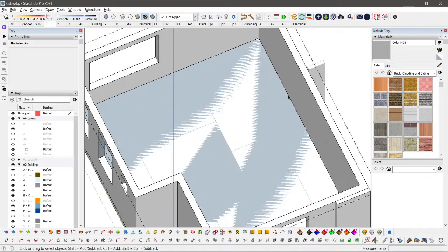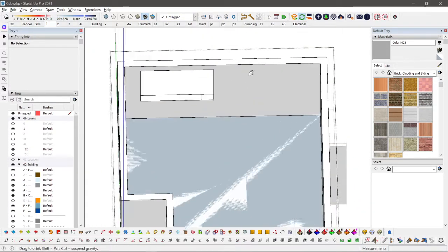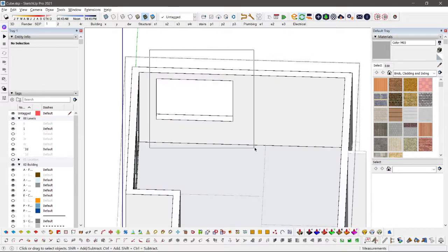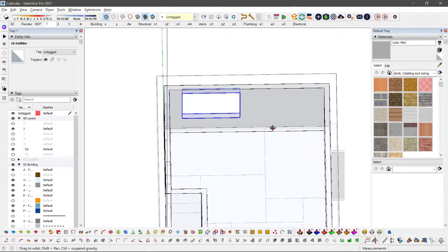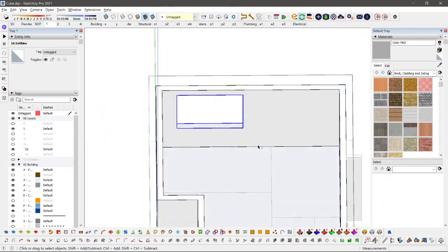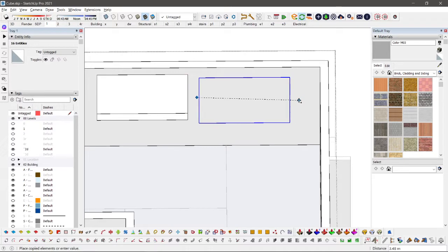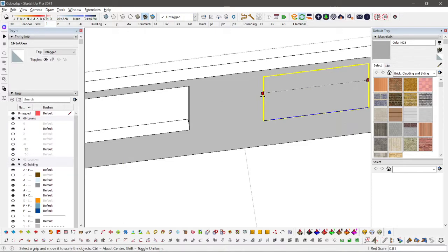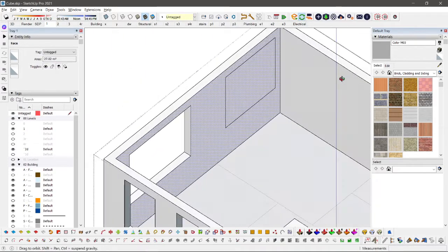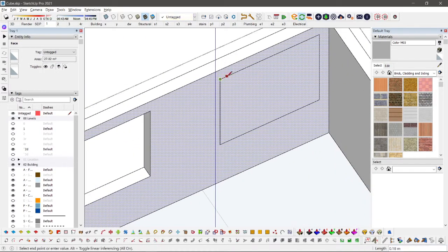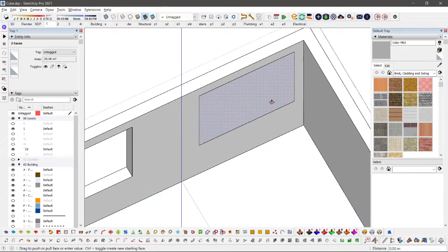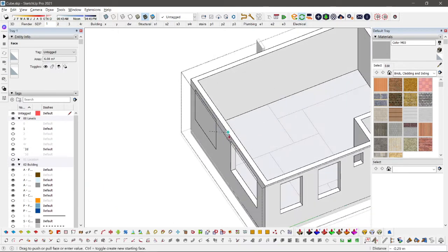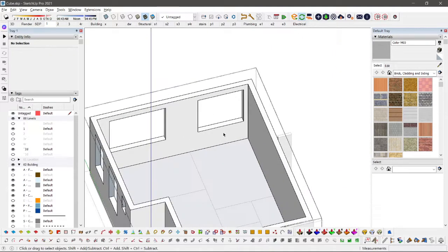And I know that this is the, let's say for example you're using the conventional method, no problem. Select that and use the X-ray to see that you are not selecting unnecessary lines. And what you could do is just copy paste by moving and holding Control. But in this case, because it was just copied, you have to trace over the line to let it know that there's a surface there. Okay? Now to push, pull, just align it with the outer wall and it will become a hole.